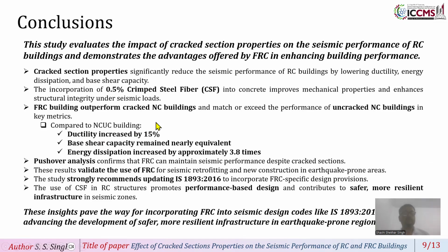In the FRC building, ductility increased by 15%, base shear capacity remained nearly equivalent, and energy dissipation increased by approximately 3.8 times. Also, the next conclusion confirms FRC can maintain seismic performance despite cracked section.